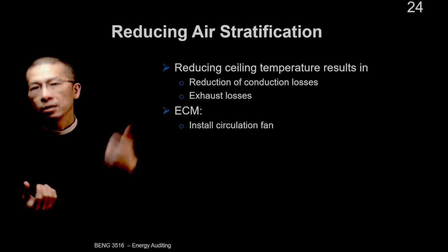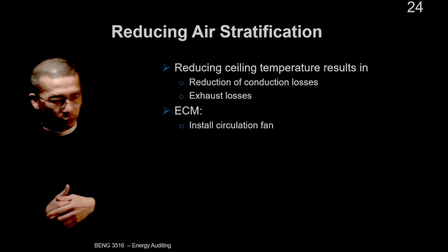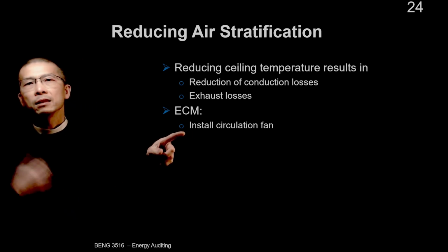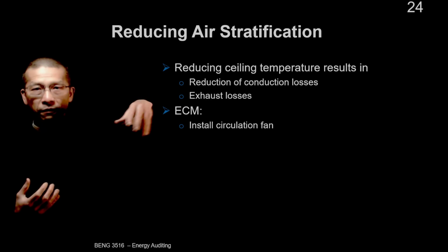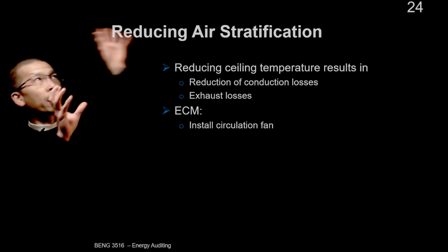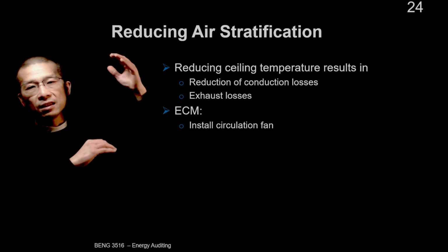So conduction, infiltration, both. Now you can see one thing we can do: install fans to reduce warm air accumulating at the ceiling area.